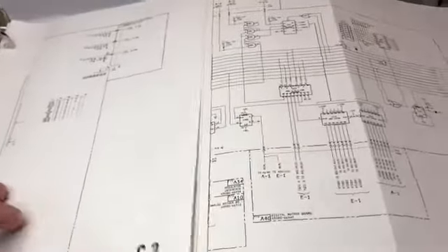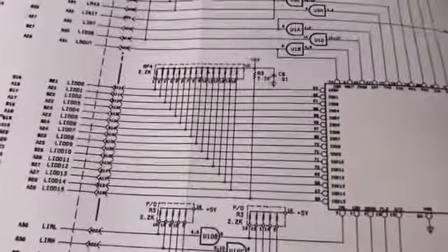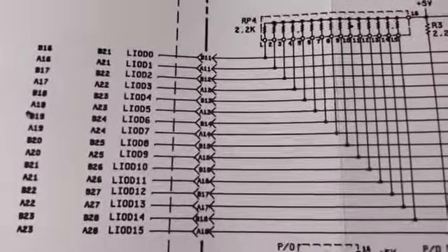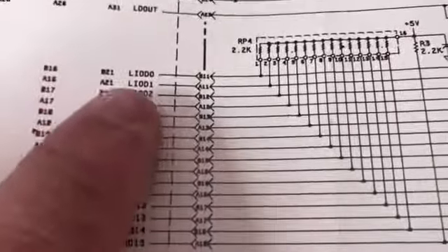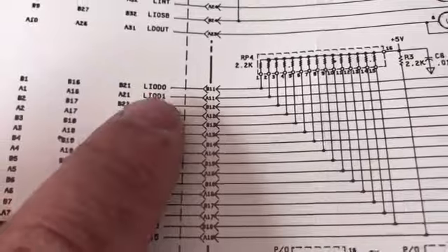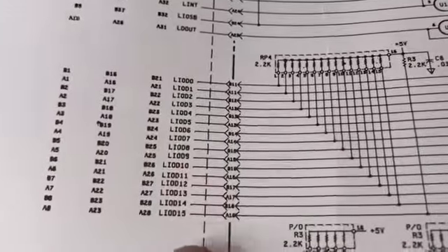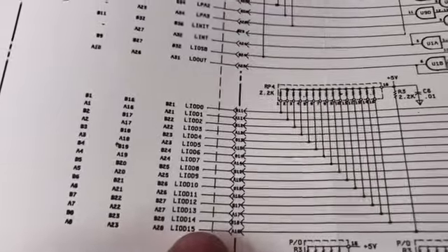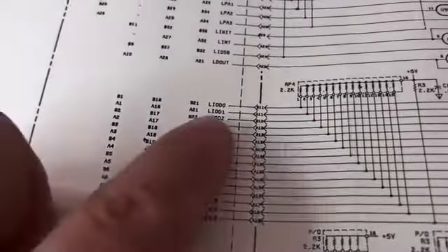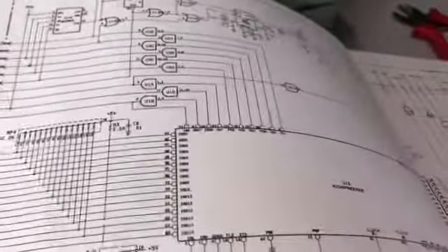So those lines are the input-output data lines for the microprocessor, exactly like that. Sorry, it's not easy to manage this big schematic. As you can see, the mnemonics is line input output data 0 to 15, so it's 16 lines. And those lines tell the microprocessor how to behave in this moment.